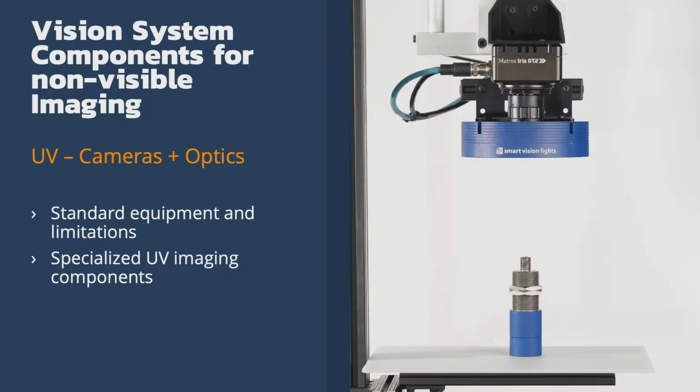Similarly, this is an Edmund Optics Tech Spec lens. It is also important to point out that you should be seeking lenses that are specifically designed for machine vision. This is because photographic and security type lenses are aimed at making visible images and outdoors. Many of these have UV blocking coatings which are necessary for security cameras and other photographic applications, but obviously will then also block the UV light when you're trying to use them for machine vision and non-visible imaging.